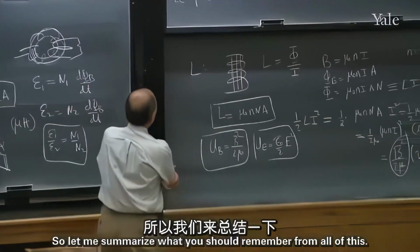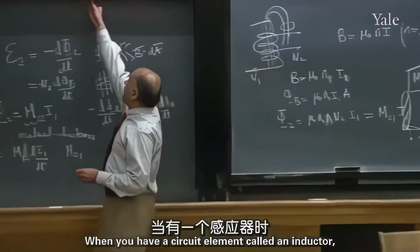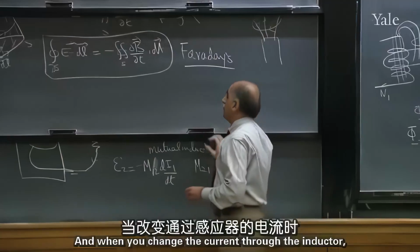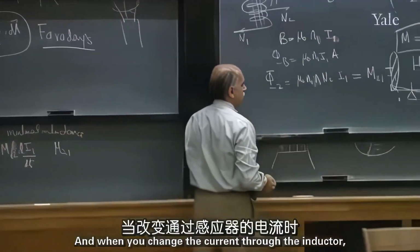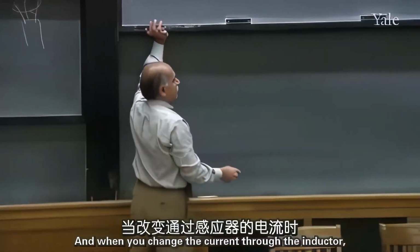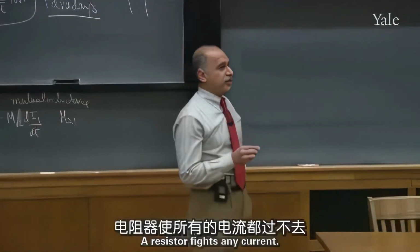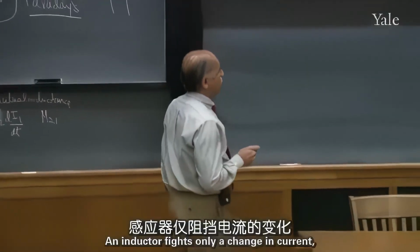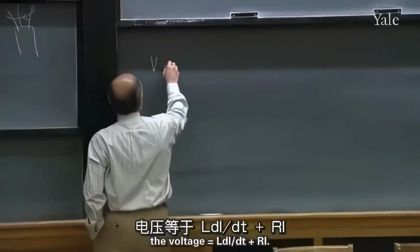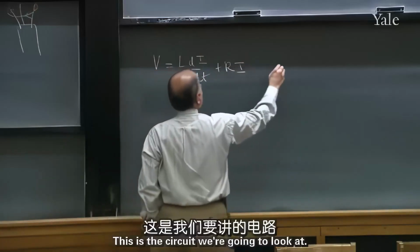So let me summarize what you should remember from all of this. A circuit element called an inductor is just a coil of wire that's wrapped around some solenoid. When you change the current through the inductor, it's going to fight it. It's not like a resistor. A resistor fights any current. An inductor fights only a change in current. So that's all summarized in this equation: the voltage is equal to L di dt plus R i. This is the circuit we're going to look at.